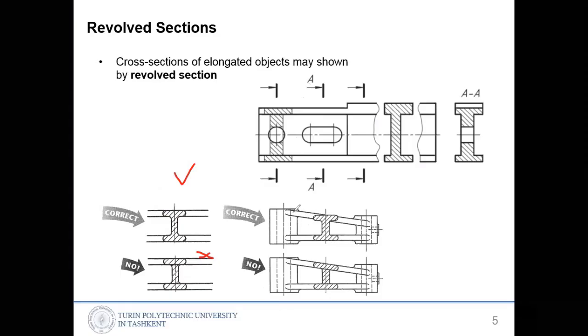And also in this structure, from the side view or front view, you're seeing a cylindric part here, and a cylindric part here, and inside there is a hole, and here is a slope. When you cut, you will see this kind of cross section. So you have to draw what you see.